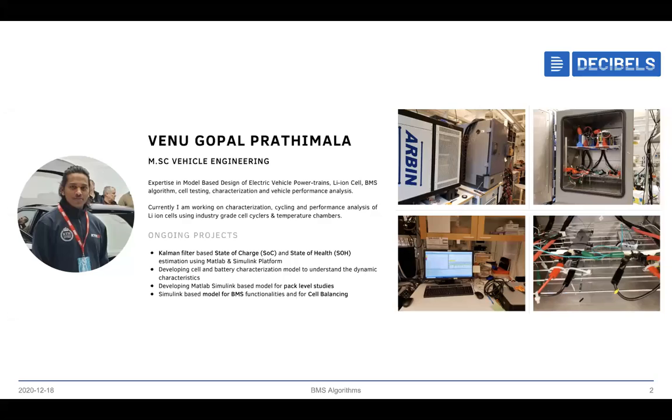Ongoing projects include estimating the state of charge using Kalman filters, developing models to understand pack-level behavior of the battery pack, and developing algorithms for protection circuits, cell balancing and state of health estimation. Some quite good outcomes are coming out of this testing.